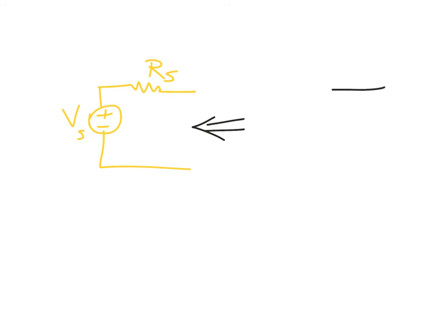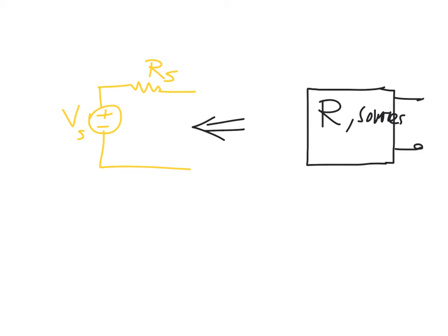Just for our knowledge, when I mentioned we have this one, this is some RS and this is Vs, the circuit actually is not as simple as just the resistance and the voltage source. As we know from the Thevenin circuit, we have this black box with many resistances and many sources, and just two terminals.